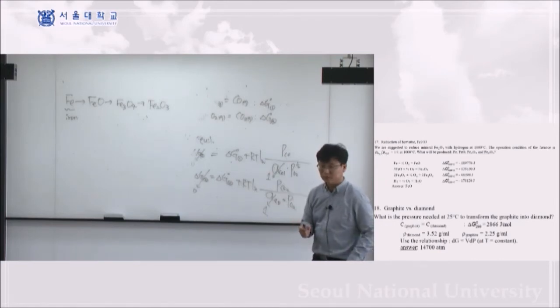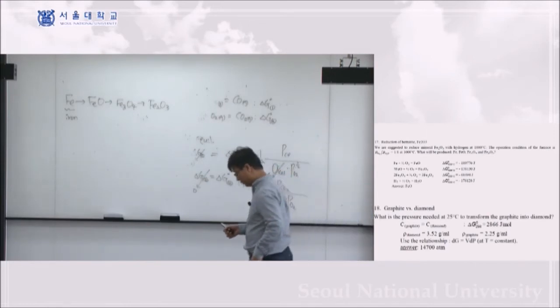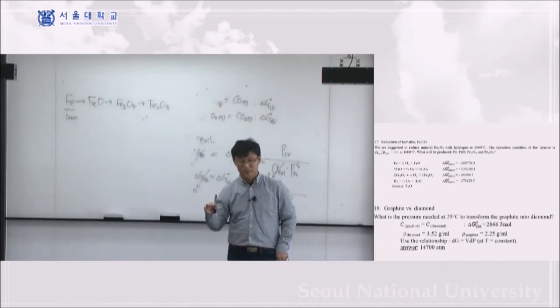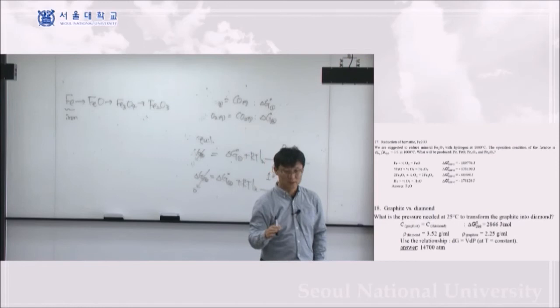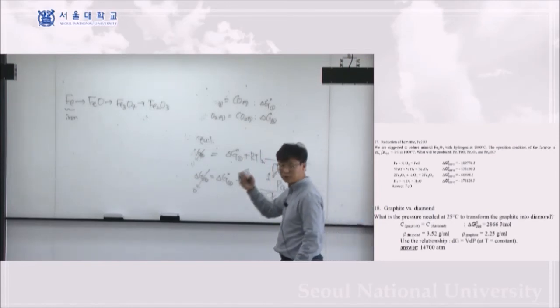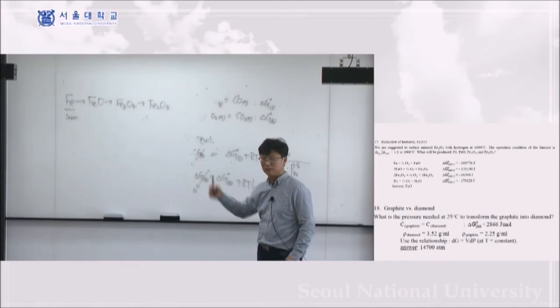So Fe is iron. You know BCC and FCC transformation of the iron, yeah? So we have iron transforming from BCC to FCC at around 900 degrees Celsius. That's the first transformation. And then if it heats up to about 1400 degrees Celsius, FCC becomes BCC again.